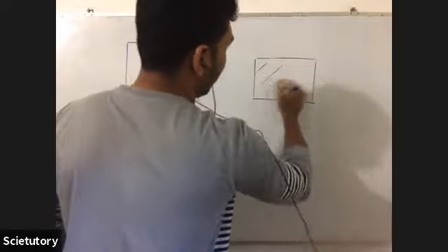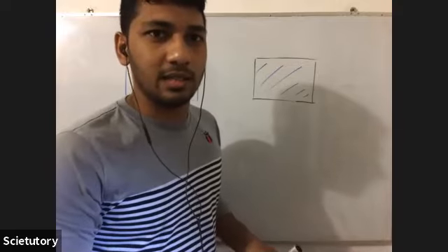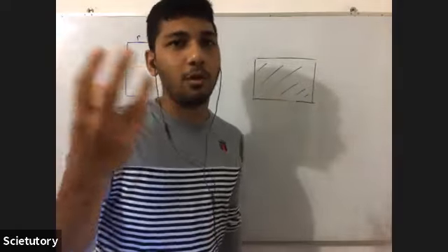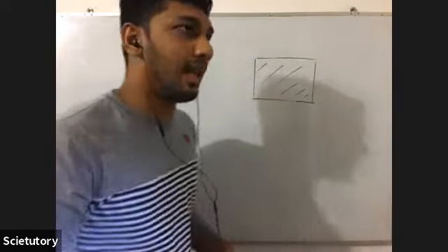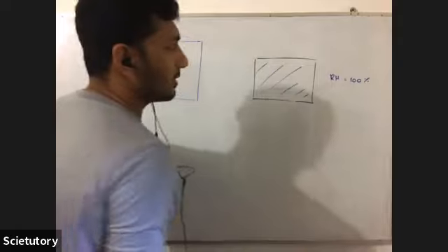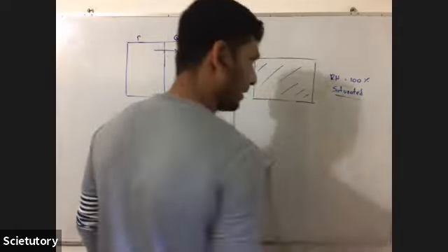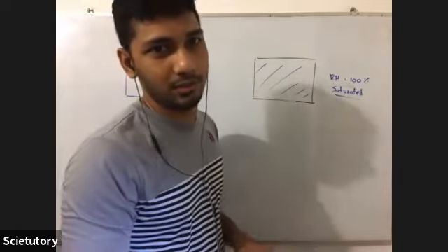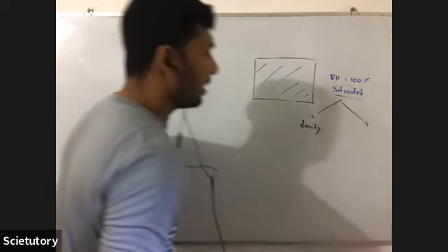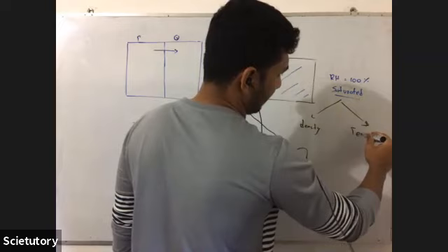So why does that happen? Because the water gets saturated. So what is getting saturated? Saturated means the water vapor cannot remain in the form of gas, so it becomes liquid. So it happens when the RH, relative humidity, is 100%. So that is actually when the water vapor is saturated. So you can actually saturate the water vapor in two ways. What are those ways? One is related to the density of the water vapor, or the mass of water vapor. The other way is related to the temperature.